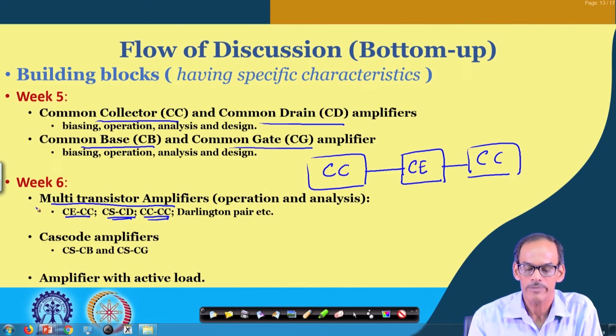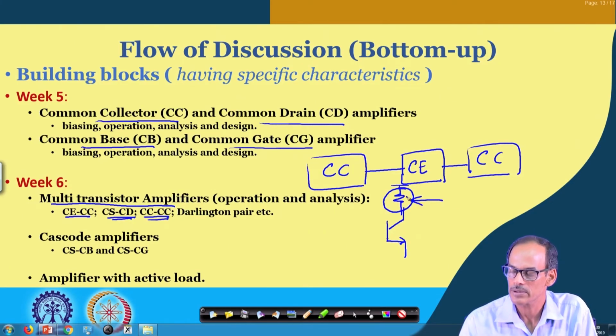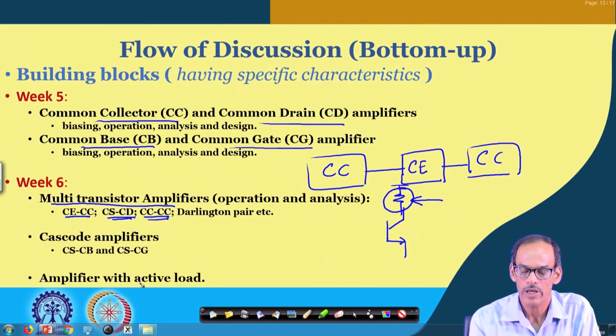And then, so far we will be discussing the connections around one transistor, and the biasing arrangements are performed by passive components. But we will see that if we always use passive components for biasing, there will be its own limitation, which invites the question: can we make a better biasing arrangement, namely what is called an active load?